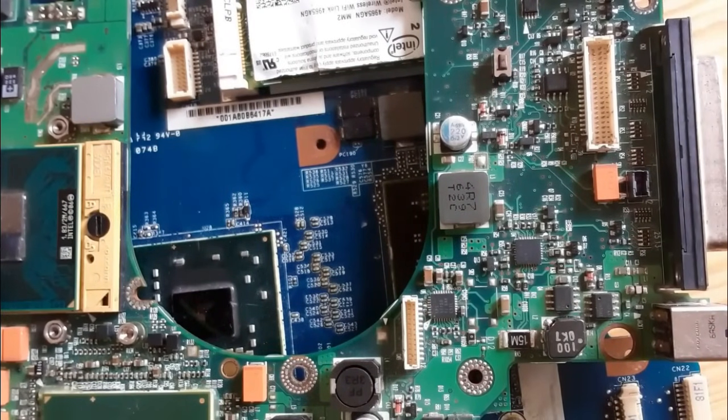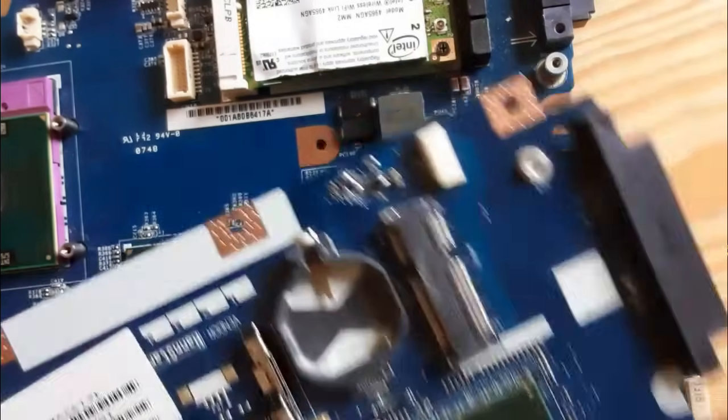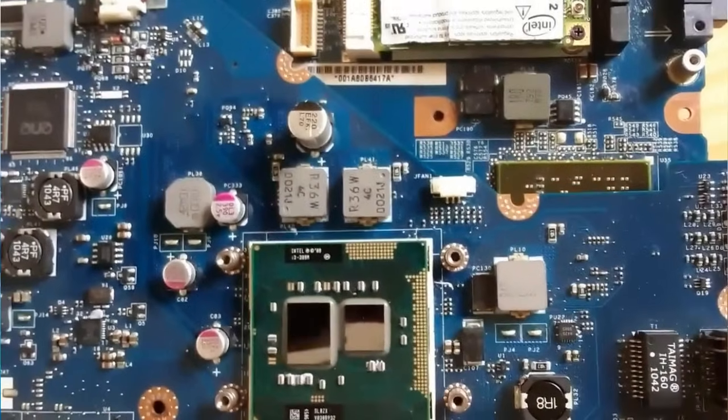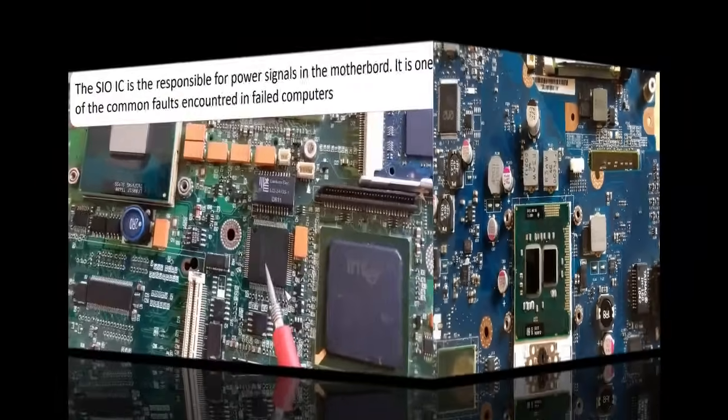As I told you before, if you find any shorted ceramic capacitor, that means the IC is damaged. You can also use your finger to check the heat of the IC. If you find heat over the IC, the IC should be replaced.